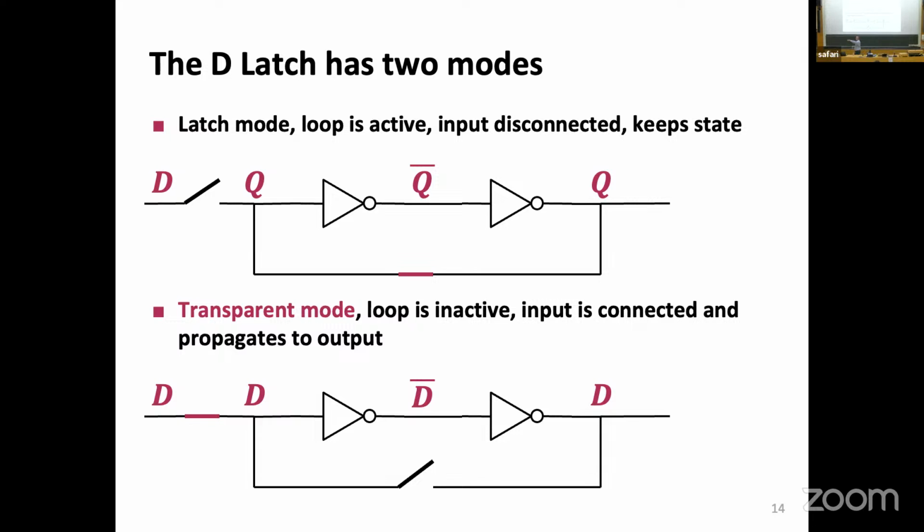There was one thing. How can we keep the current flowing in this loop without creating a perpetual motion? It's not a perpetual motion machine because these gates have their own supplies. This one is connected internally. We remember there was this one lecture where I said, this is the only time we talk about it, but there will be transistors that are connected to a power supply. So they draw current from there, actively. They consume power actually keeping it. It's not like data freely circulates like that. It's actively being kept this way. And if you turn off the power, this thing will lose the content of the memory.